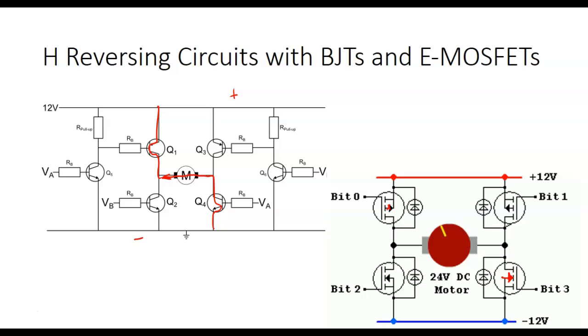What's nice about this is we have a thing with motors, and we're fixing to look at that in a minute, James. It's called plugging. Plugging is when you reverse the direction of a motor without it coming to a complete stop. And we talked about this. Motors pull a lot of current to get them started. We call it starting current.